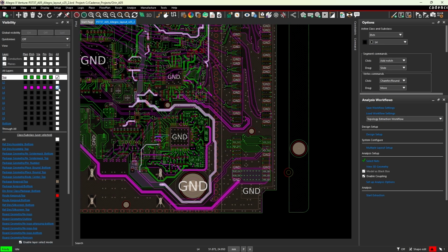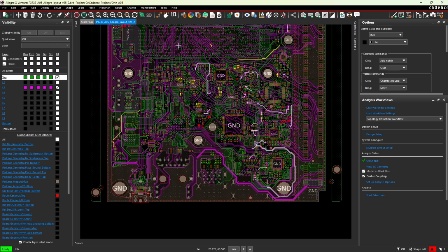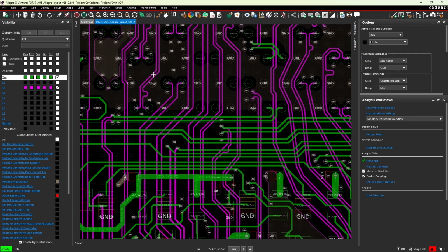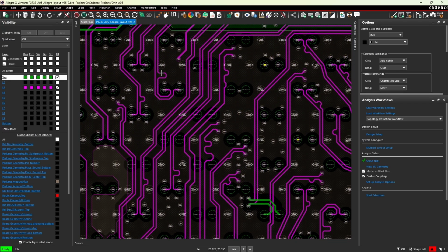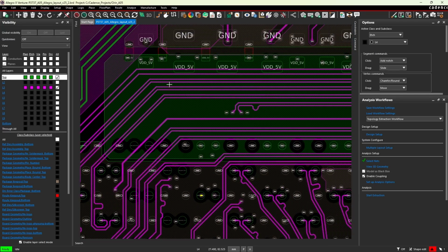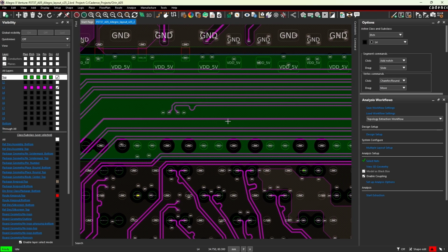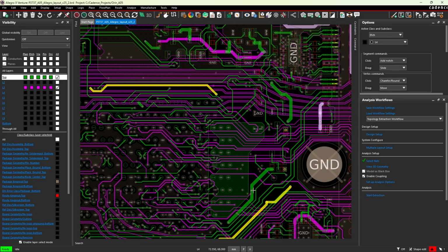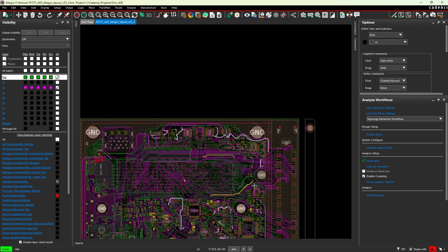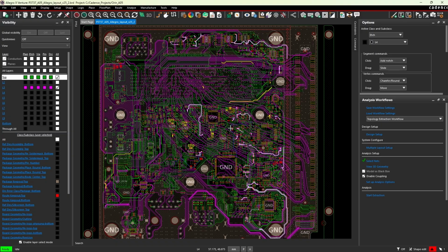A lot of people are afraid of PCIe because you have to route them according to fiber weave and all that. There are many things that can go wrong if you do not route your high speed signals very well. We're talking about 20 gigabits per second and higher, although technically you are in the RF domain above 2.5 gigahertz or so, or above 1 gigahertz. But at 20 and 40 gigabits per second, you really have to pay attention to the field. In fact, you're routing microwave fields at this point, at PCIe Gen 4, Gen 5. So that's an overview of the board.